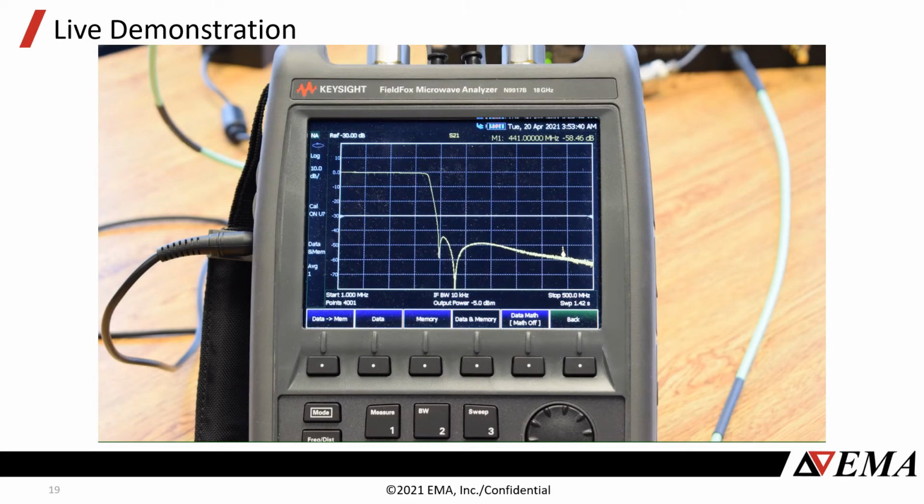Here is the S21 of the low-pass filter we'll use to mitigate the interference. On the right side of the plot, we placed a marker at the location of our third harmonic, and we can see that the low-pass filter will suppress it by a little under 60 dB.